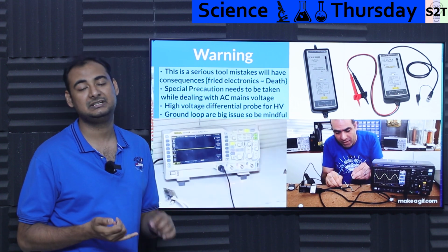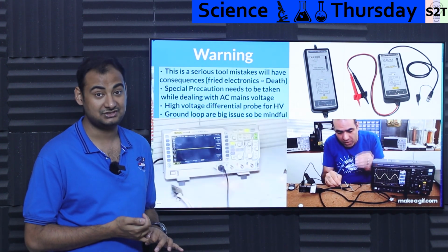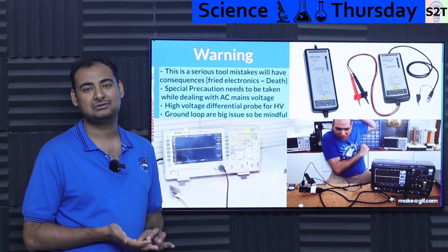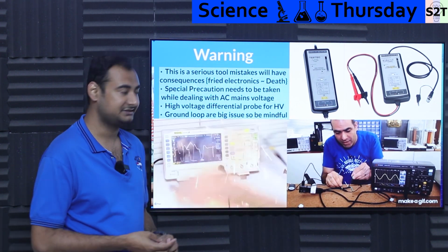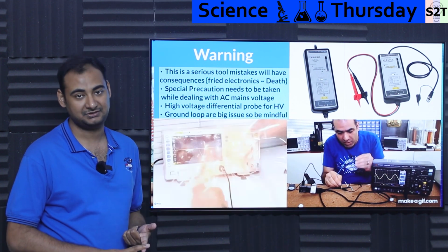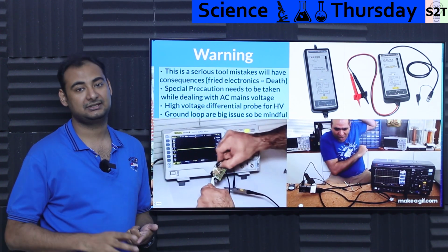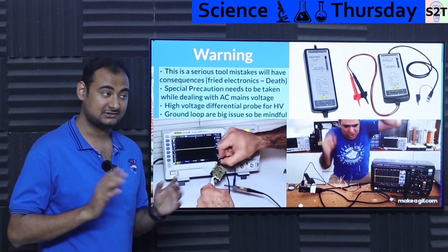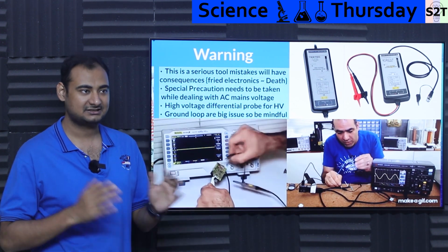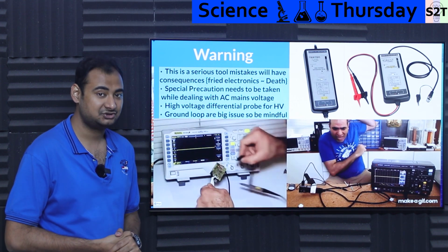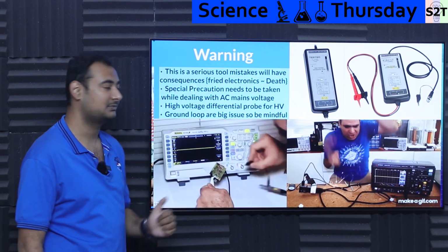And if you are an individual who's dealing with high voltage DC, God help you. If you're an individual who's dealing with motor drivers and power electronics, you have to be very serious here. Special precautions have to be done. Heck, even in low voltage, you could fry your system if it's connected to USB. As long as it's battery power, both things are battery power, you good. The moment something gets connected to ground, you have to be exponentially careful. You have to take special precautions.